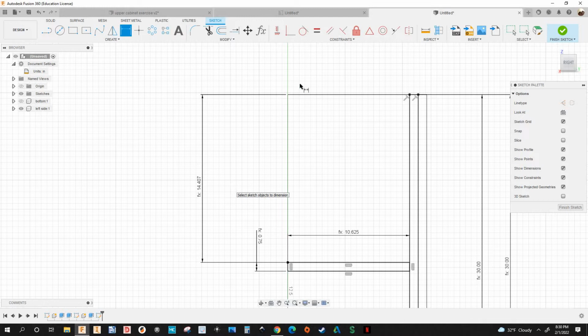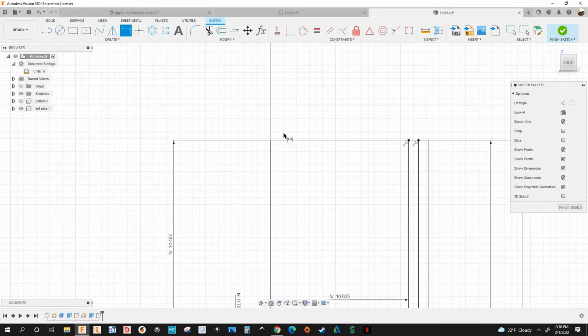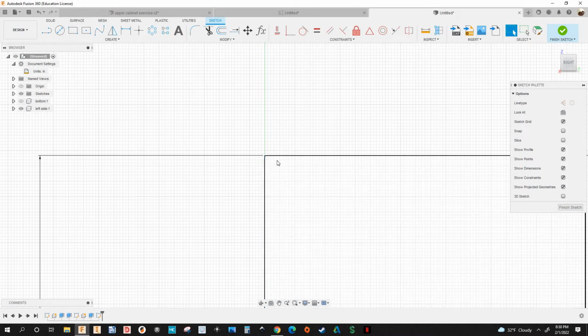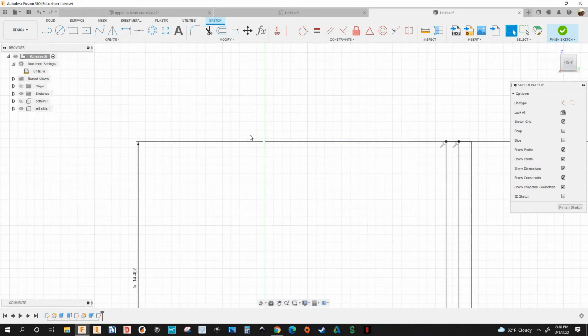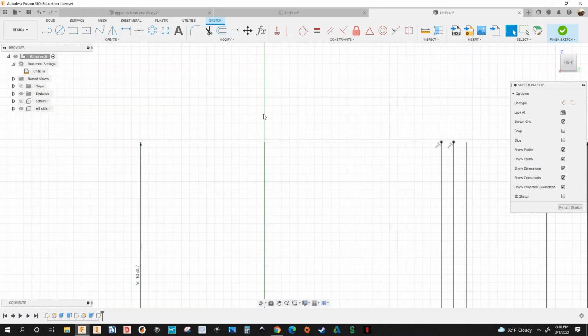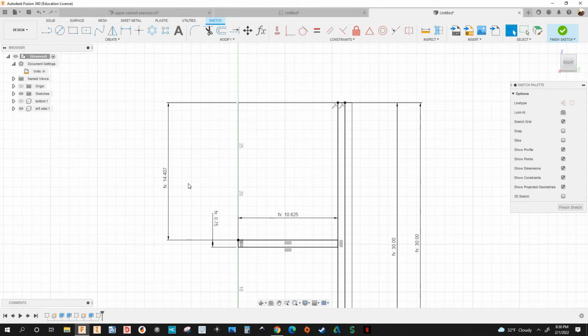Okay. Because remember this side panel is gonna go into the top. So there's gonna be 4 millimeters right here. So I'm adding the depth of the groove, right, which is 4 millimeters. Okay, so I got this distance now.